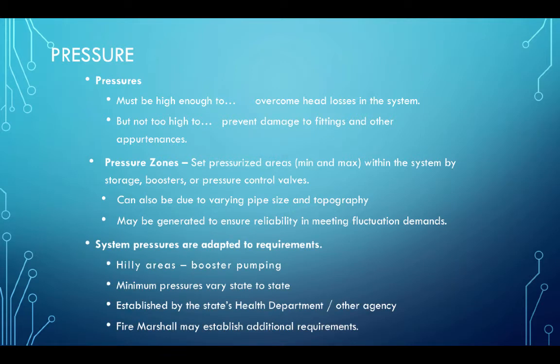System pressures get adapted to requirements, so in hilly areas there's often booster pumping and pressure reducing valving. Minimum pressures vary from state to state, but they're not going to vary a lot, which isn't to say that you can just memorize one and get away with it. Just be aware that as you move to different locales, the minimum required pressures can vary.